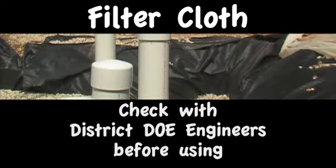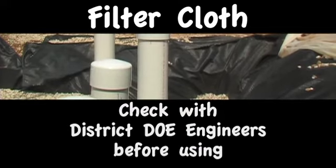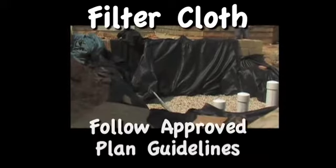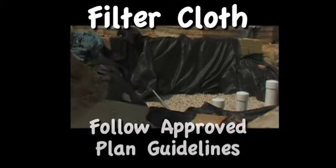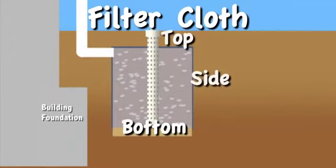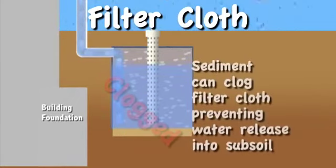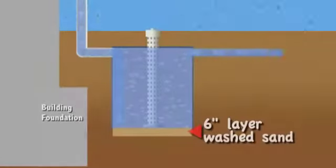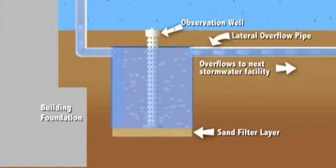Contractors and engineers should consult with district stormwater engineers prior to using filter cloth and follow the guidelines in the approved stormwater plan. Woven monofilament filter cloth may be installed on the top, sides, and bottom of the infiltration device, but must meet district code requirements. Improper filter cloth may clog and prevent infiltration. A 6-inch layer of washed sand is the preferred bottom filter layer.